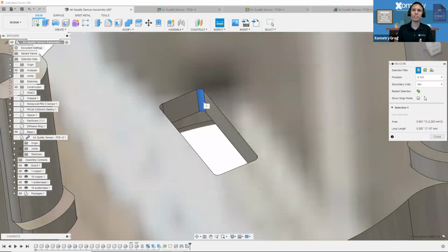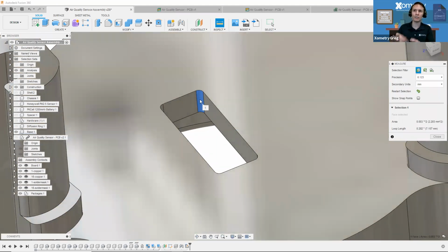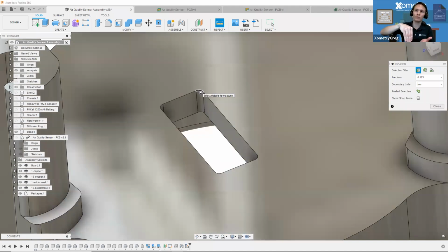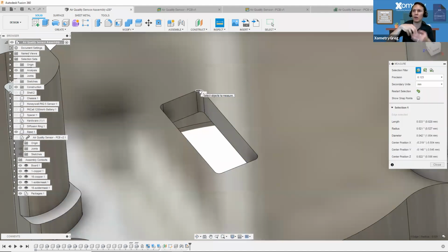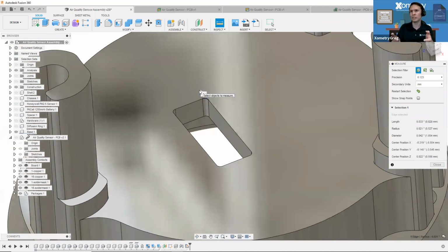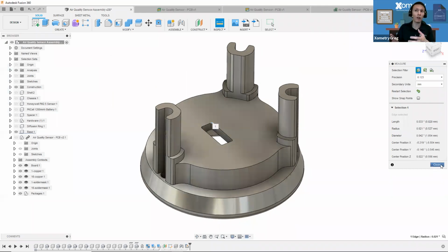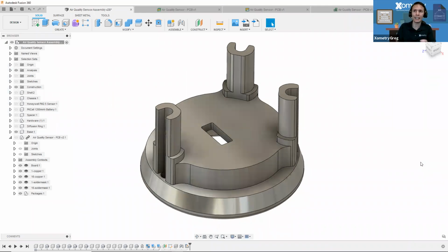And when I'm CNC machining, of course, I'm using a cylindrical end mill tool to drive down into the part and then move across that part, removing material. So all those internal corners do have to have a round to them. When you have a sharp internal corner, that's something that you need another process like EDM to create, and that can add significant expense to your part. So always make sure you have rounded internal corners if you're doing CNC machining.